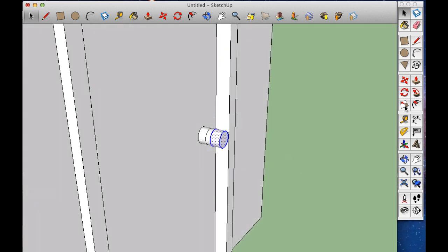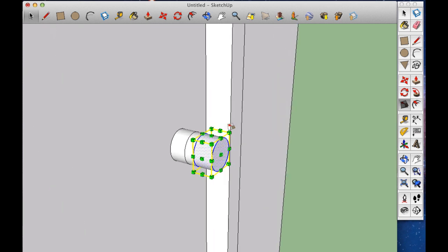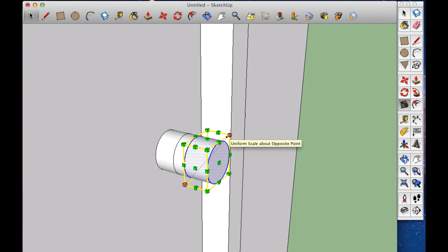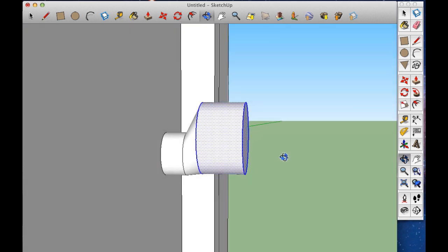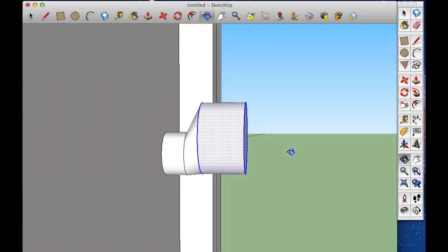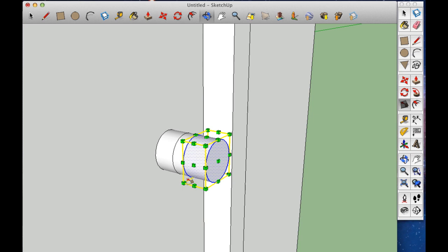And then I'm going to grab the Scale tool off the toolbar, and you'll see if I hover over the corner, it's kind of hard to tell here. Zoom in a little farther, but you can see the black diagonal line running through there that shows that I'm going to uniform scale, meaning it's all going to stay the same size and proportion. And then if I scale up, it gets all weird there, like that, because it's scaling from the other point.